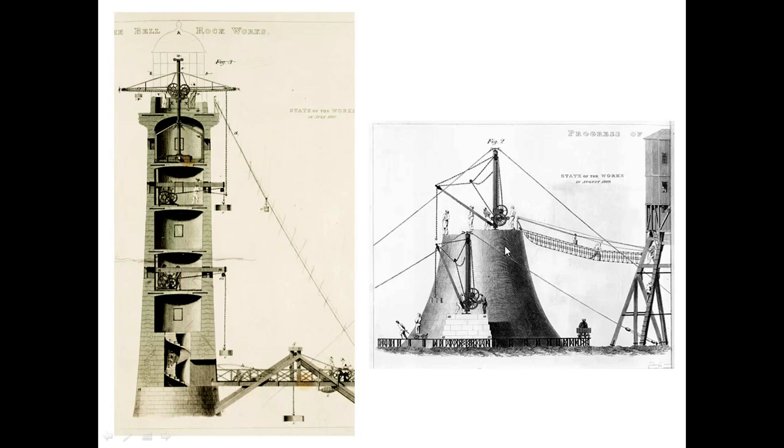The other thing they discovered when they were experimenting with the lateral load of waves against the structure, and they did this by making physical models and throwing buckets of water at them, they discovered, which you'll find quite often in structure, that this curve was a piece of pure geometry. It's a parabola, parabolic curve, beg your pardon. The parabolic curve turned out to be the most efficient curve to resist wave impact.